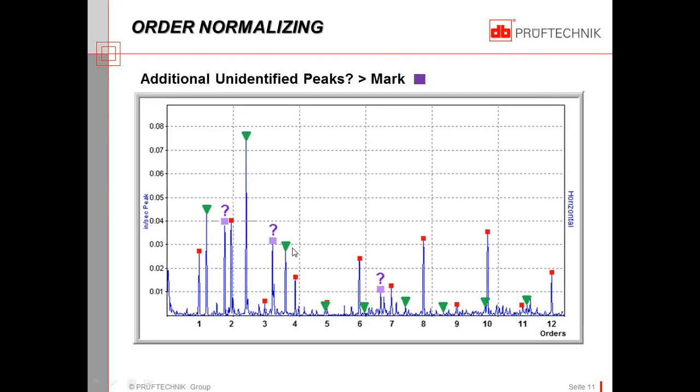And of course, then it would be up to the analyst to dig a little deeper and see, are these related to this machine? Is the vibration being transferred from another machine through a common base? Or is it perhaps the onset of a bearing problem or harmonics of belt frequency? So this is the technique of order normalizing spectral data, and I think it's very worthwhile, something that should be encouraged for day-to-day monitoring of machinery vibration.